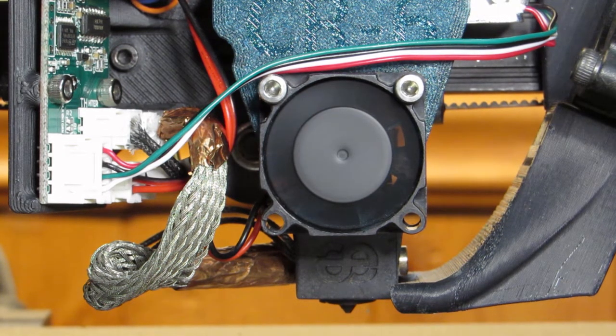But based on observation of printer behavior, it does appear that if you pull on the filament going into the hot end, or you pull on the Bowden tube connected to the hot end, it's the same as pushing on the nozzle. As far as the diving board's concerned, it can't tell the difference. The diving board does not know whether it's being pulled up or pushed up. It just knows the resistance changes when the diving board is strained.